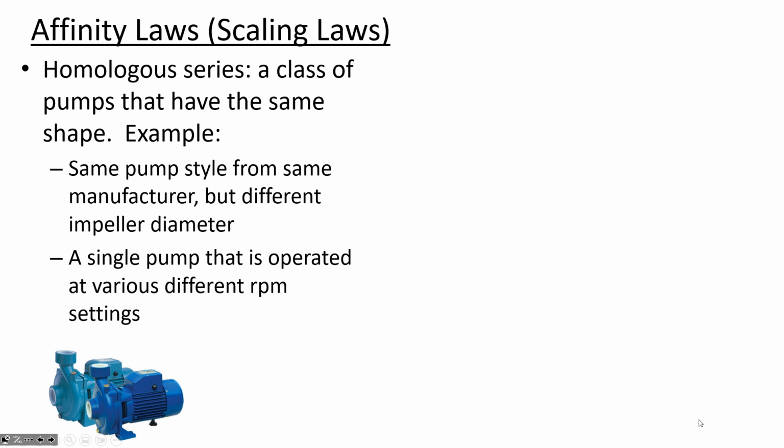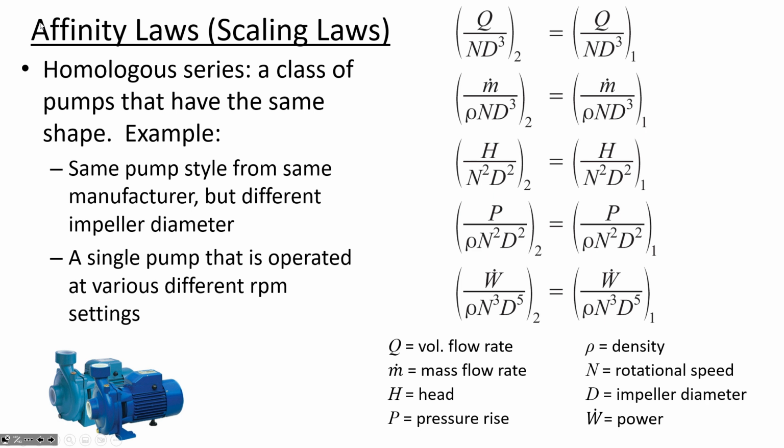These related pumps can be understood with what are known as scaling laws or affinity laws. That's just that if you understand the performance of a pump under one set of conditions, then you can calculate numerically, because of these scaling laws, how it's going to perform at a different range of conditions. So these formulas, I've screen captured out of the FE equation book. Your textbook also has these equations with different variables, but this is just to get you familiar with how it looks from the FE reference manual, because it's likely you could see a problem related to this on the FE.